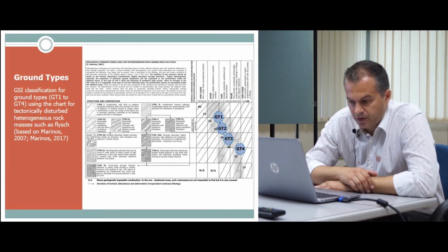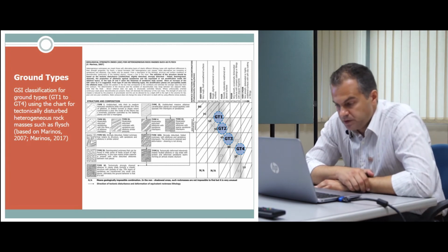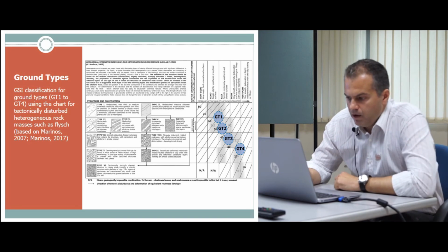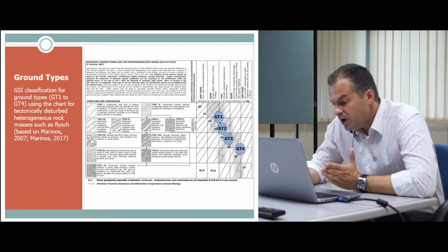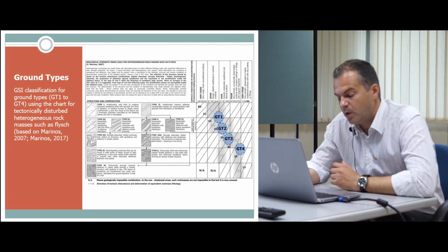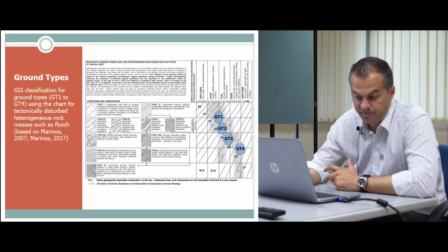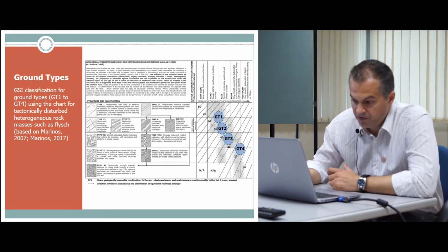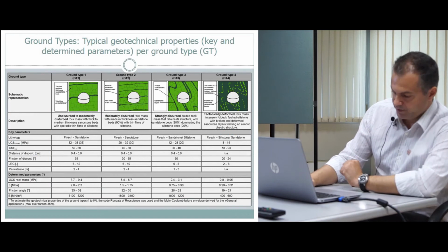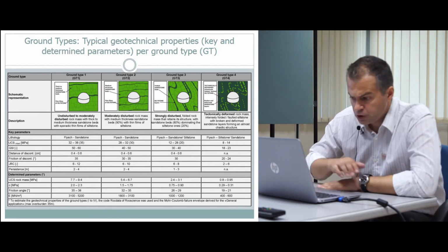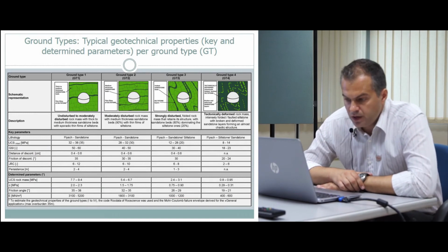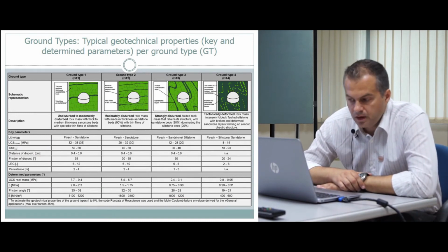Here the example is a maximum overburden of 35 meters, so we can find the equivalent friction angle and cohesion of these rock masses. But we will use these rock mass properties if the rock mass behaves isotropically. If it does not behave isotropically, then we have to use other parameters of the discontinuities if it is gravity-driven failures.